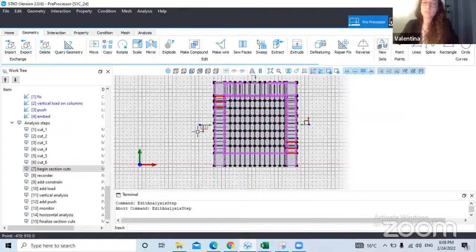So the problem was how to measure shear in the frame column where we have additional shear due to the infill. It's my field of interest. And as I'm working with a 2D continuum model, in comparison with 1D when we use fiber sections, it's much more complicated here to measure shear. What Massimo offered me and helped me with was a script that allows us to measure shear.